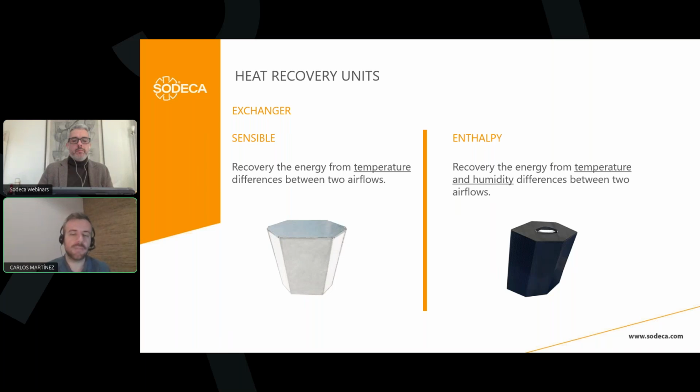Okay, so probably enthalpy exchangers are more suitable for projects in places with high humidity rates, for example on the coasts, or in places where the difference between outside and inside humidity is big. For example, I can imagine a gym, or a bar, or some place where the humidity will increase because of the presence of people, but outside is not too high humidity.